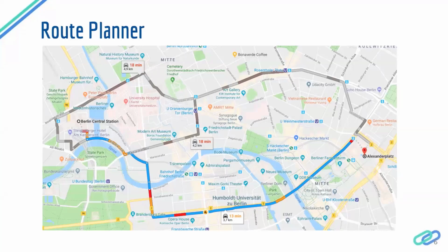So let's see how this information is helpful. If we know what the landmarks around us are and everything that is surrounding us, it becomes easier for the car to localize and also to plan which lanes to take, which lanes not to take, and which exits to take. All of this information is in the high-level route planner. These maps are also updated in real time so that we know about traffic jams, if there is construction going on, or if a road is suddenly blocked. All of this information is needed for the route planner, so that is used in this layer.